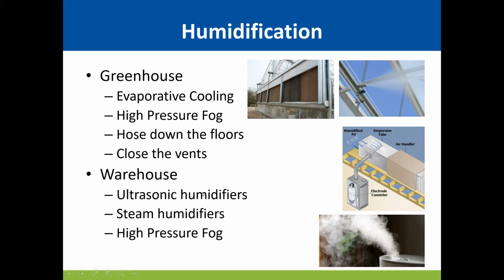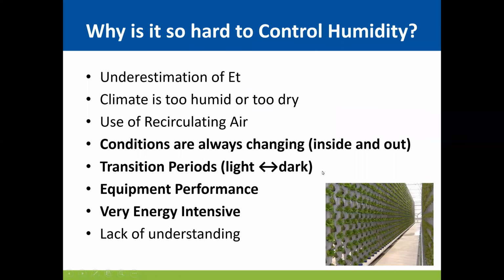With a warehouse, we tend to do things on a smaller scale or a little more gently, using ultrasonic humidifiers, steam humidifiers that can even be placed in the air handling, air conditioning equipment. And some people do use high pressure fog, say in their clone rooms. So why the heck is it so hard to control humidity?